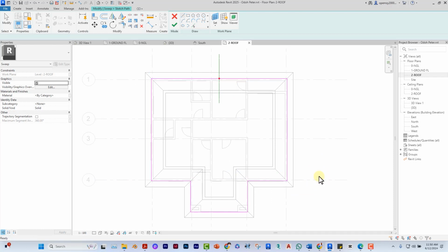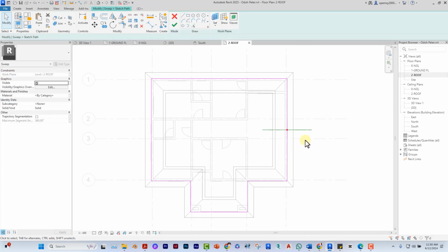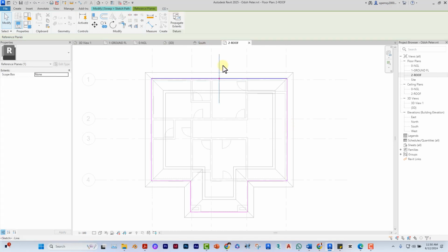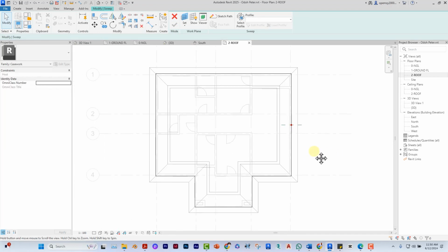You can see the line, and you can also see a red dot somewhere on the line. I've pressed escape twice. Now before you click finish, this red section line, if you click on it, you can actually drag it around the line. And this is important in case you want to work in any particular view, for example. This can only be done before you click finish edit mode for the sketch part. Because I started drawing from the back, the first line you draw is where this section is going to be cut. But I can click on it and drag it to this end if this is where I want to work from. And after this, you click finish, and then the sketch part becomes black. That means you finish working on the part.